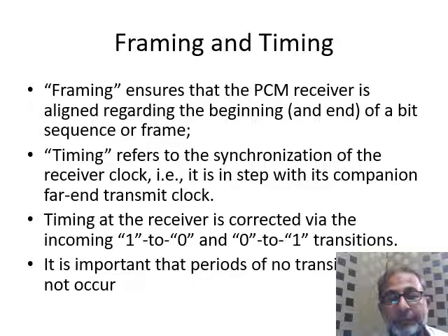Now, what is the difference between framing and timing? Framing ensures that the PCM receiver is aligned regarding the beginning and end of a bit sequence or frame, so that we know that a new frame is starting.